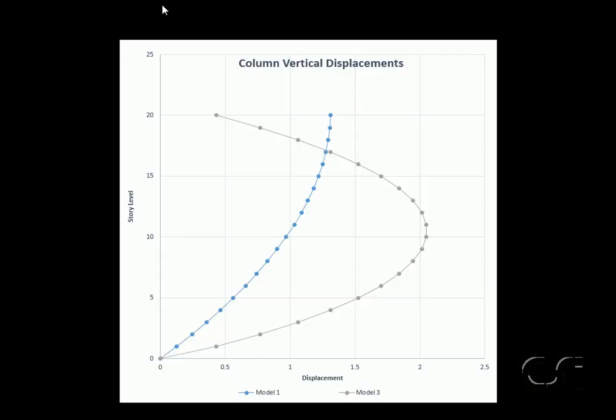To emphasize this point, let's take a closer look at the displacements for the second story. We are going to compare the interstory deformations for analysis case 1 and analysis case 3. Remember that analysis case 1 is where the loads are applied after the building is built, and analysis case 3 includes creep and shrinkage with stage construction.